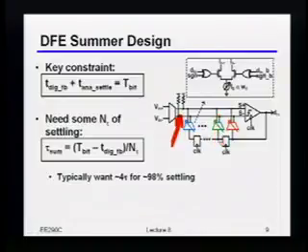Okay, so you can imagine that if I really did something like this, well, which one are you going to have to use? The shortest one. In terms of the settling time, or shortest in terms of the digital delay? Digital delay. No, it's actually the shortest settling time. Right, because let's say that this loop is longer, and I want that to settle within whatever time is left. Right? So we'll actually talk about exactly that issue in 1 second, because it turns out you can imagine that it is usually longer than the clock to Q delay of the flop. Right? Because for all intents and purposes, this is a flip-flop, just with a really small input voltage. Right?